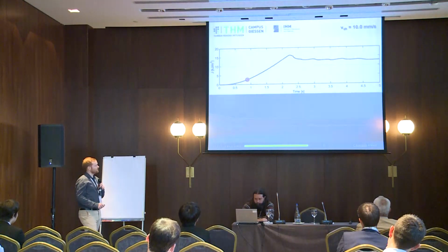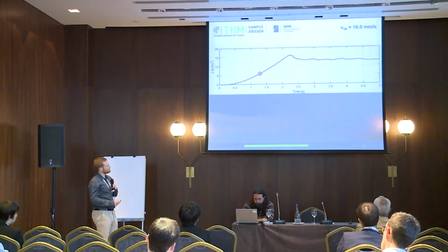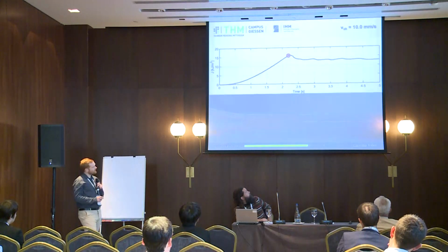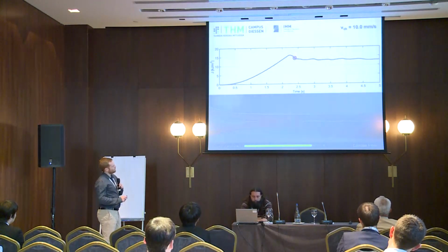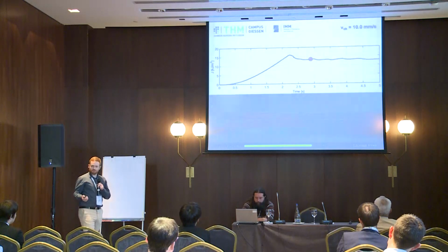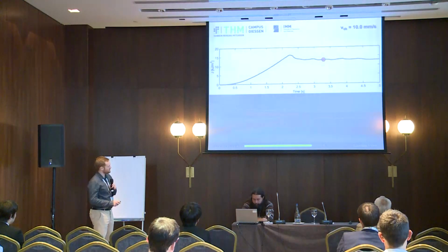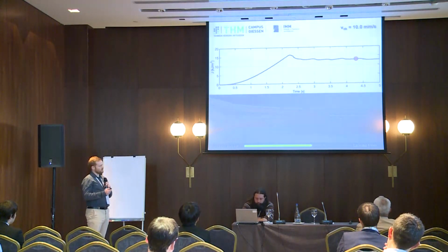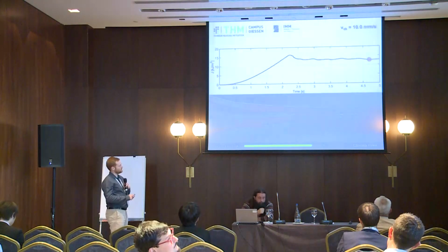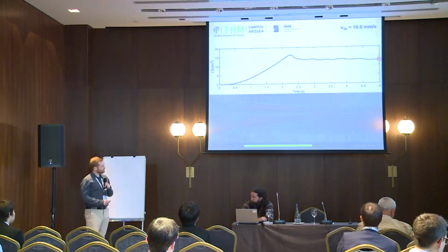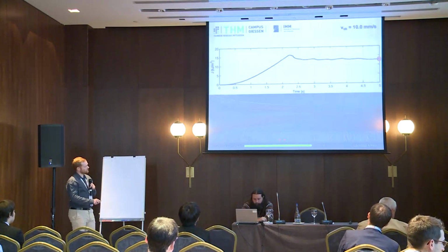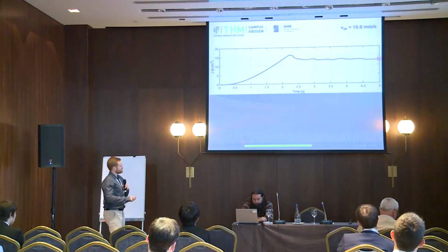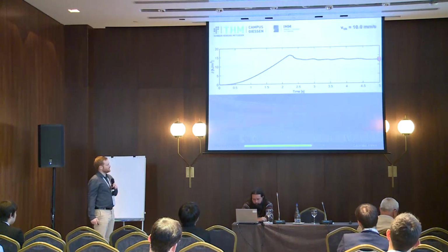And now we're increasing test speed again, 10 millimeters per second. You see J over time again, and the specimen here. And necking and blunting appears. At maximum J, we have one overcritical crack jump, and stick-slip fracture disappears. So it's just between some regions of crosshead speeds that we have distinctive stick-slip fracture, and we see no rest lines anymore, or no changing in rough and flat regions in the fracture patterns.